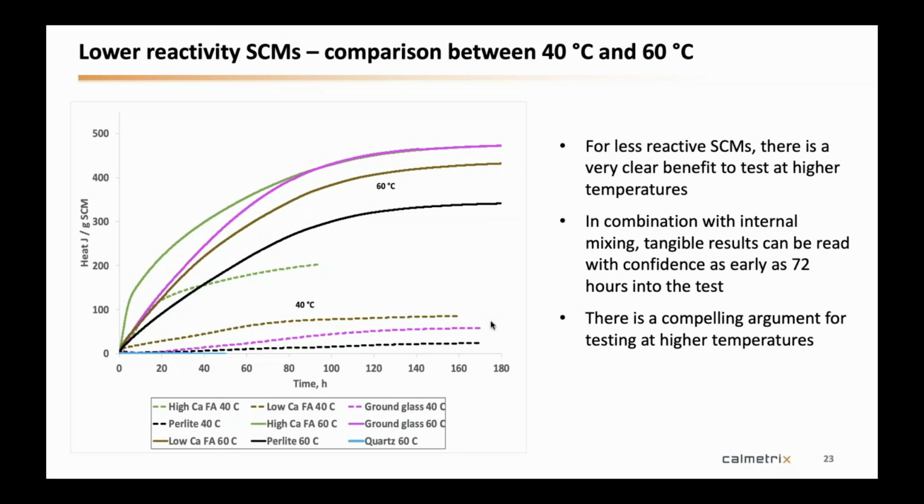The internal mixing, Era's question is for everyone else. Internal mixing allows capture of the initial critical aluminate hydration reactions. Just how early can meaningful heat versus time data be collected in your system? So when you have the internal mixer, you capture it from time zero, since the time the water hits the first grain of cement. However, of course, here again there's an overlap.